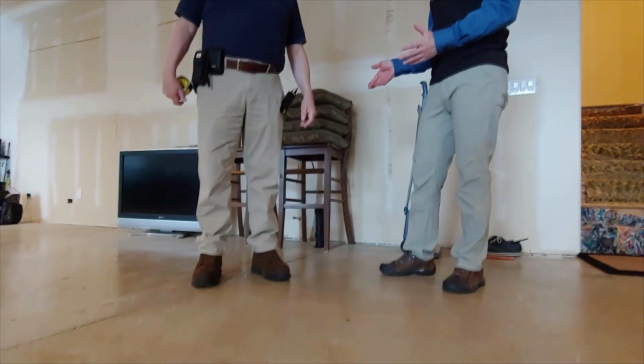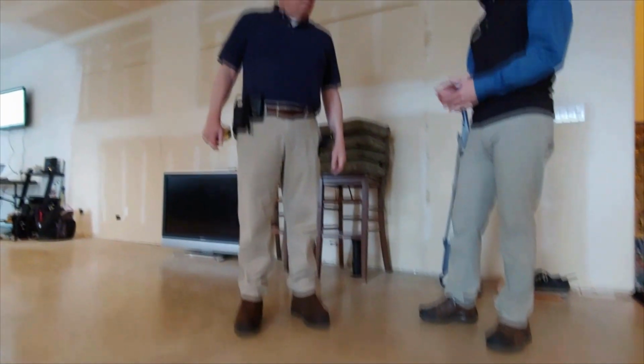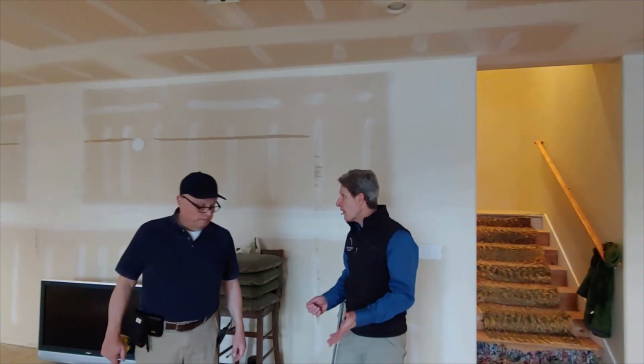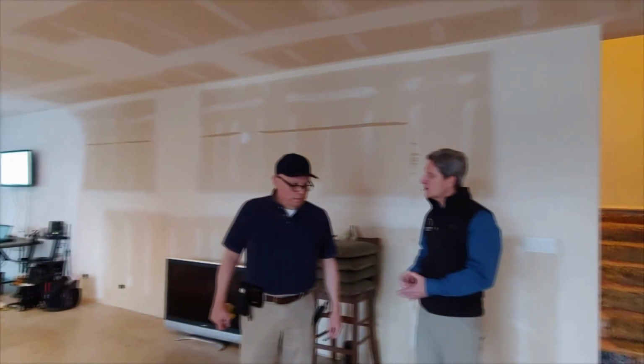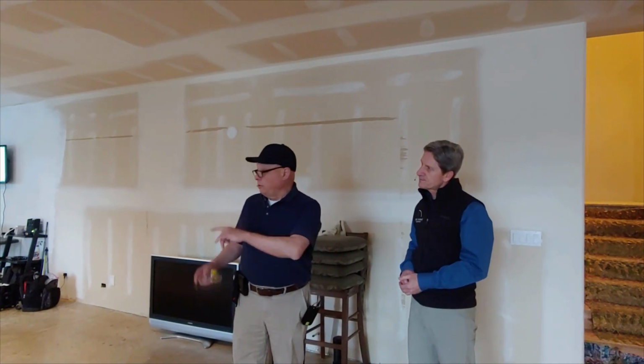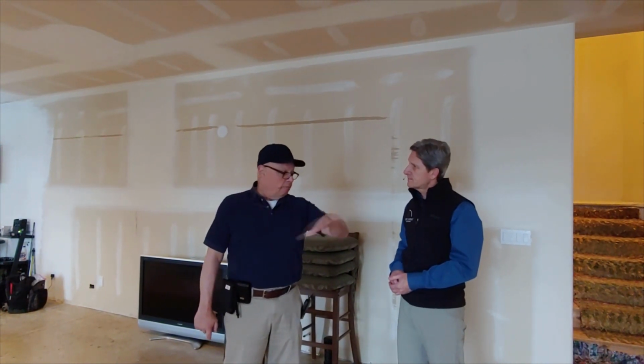What if this floor is not on the level? Maybe it's sloped for whatever reason. Maybe it was an older structure and it was maybe a garage even. How would you manage that when you put it into Chief Architect software? In the program, I'm going to use the tallest dimension, and then I'll work back up from there.